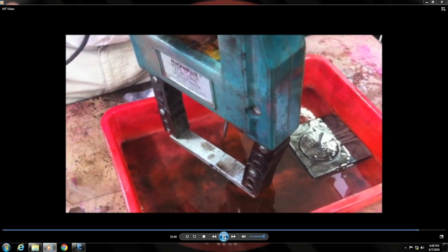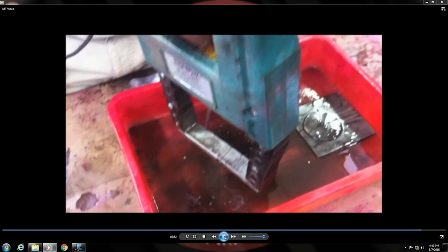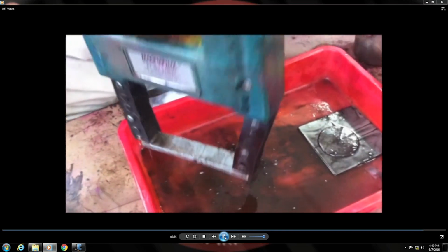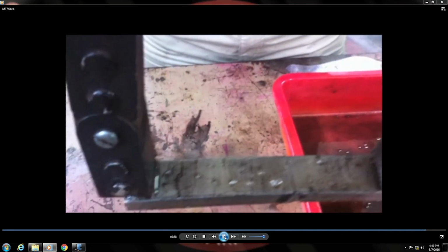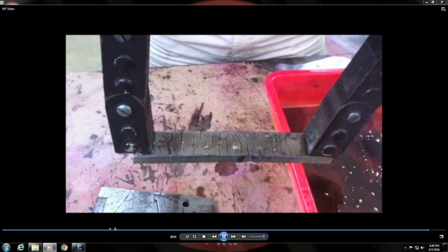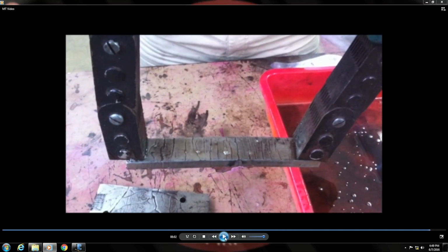This is another small part, again the same thing you could see, it's being magnetized and the particles are applied, and what you could not see by naked eye now you could see. Again you could see the directionality. Okay. So, these cracks are all in this direction, which is perpendicular to the direction which is connecting these two legs. So, this is the direction of the magnetic field, a line connecting these two legs, and these cracks are all perpendicular to that direction, and that is why you get very strong indications of these cracks.